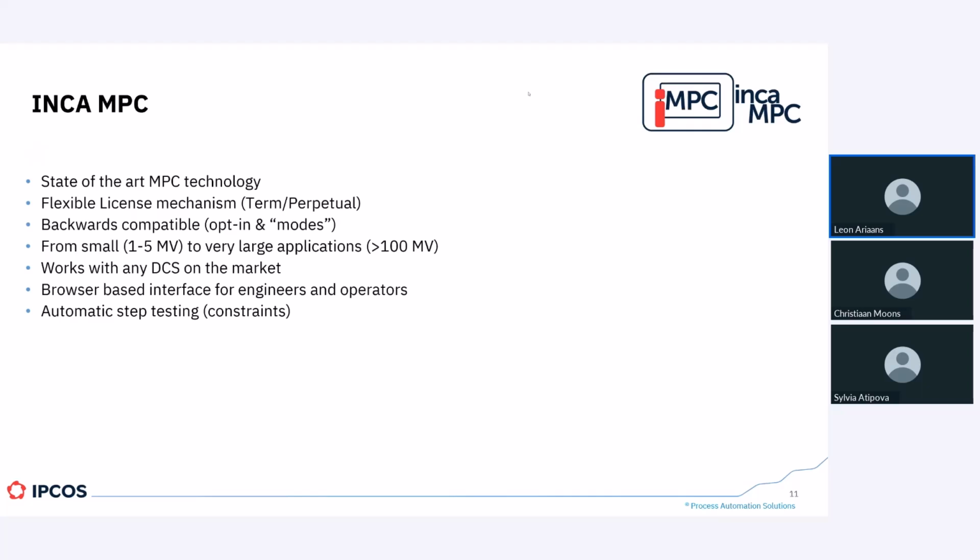What it takes is an initial model of the plant where you need to have a rough idea of what the gains are, of what the speed of the responses, the time constants, are. But if you have a rough model like that, you can ask INCA MPC to do the application of steps for you. So it will generate patterns of steps that you can use in your identification. And it will try to keep your process between the process limits based on the model that you have.